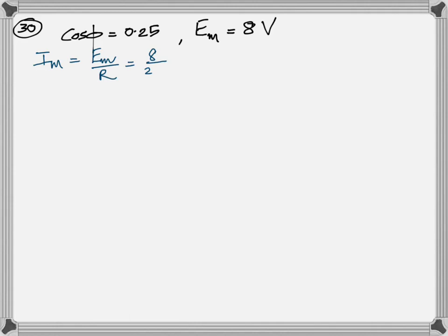So at resonance, remember the curve for resonance? The resonance curve goes up, and at resonance is when the current is maximum, and that's because the impedance is minimum. And what's its value? Just the resistance in the circuit. Very important point. So I got the maximum current using that concept.